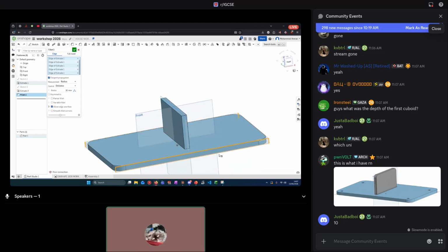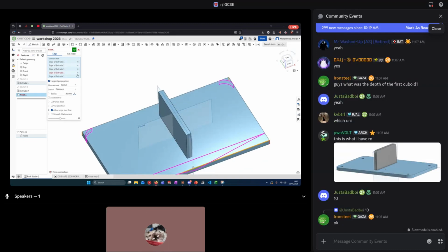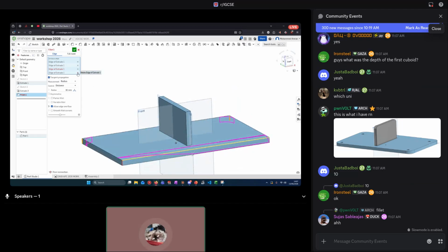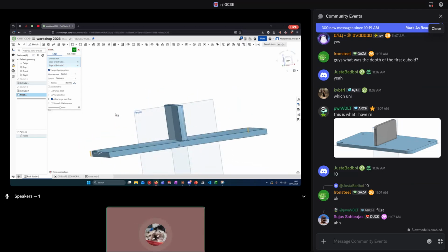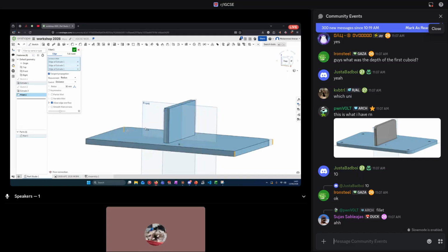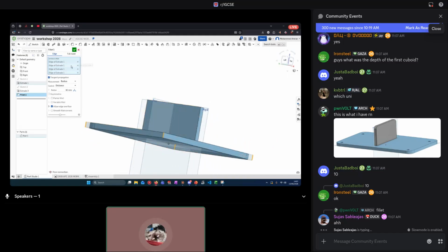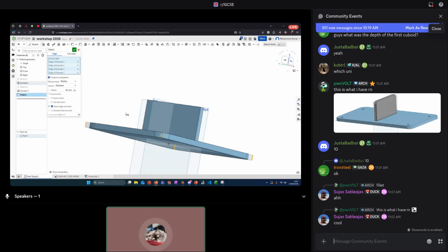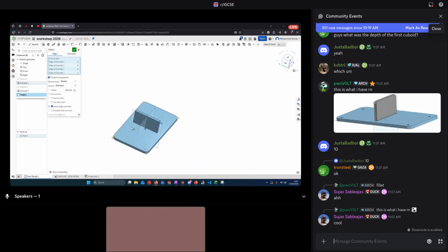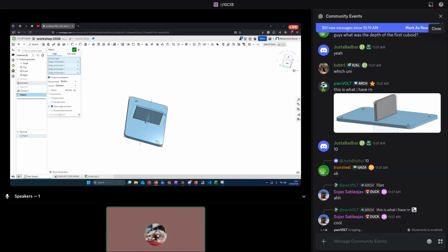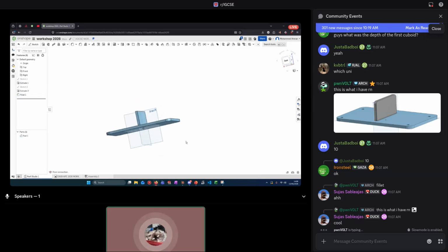Let's say you accidentally selected a part wrong. Let's say you selected this edge instead. You're going to come right here and then click delete edge, and then delete. And then you're going to reselect them again. Right here you can deselect the parts that you selected. Once you've selected all 4 corners of the shape, we're going to click the check mark. So now all 4 corners are rounded.